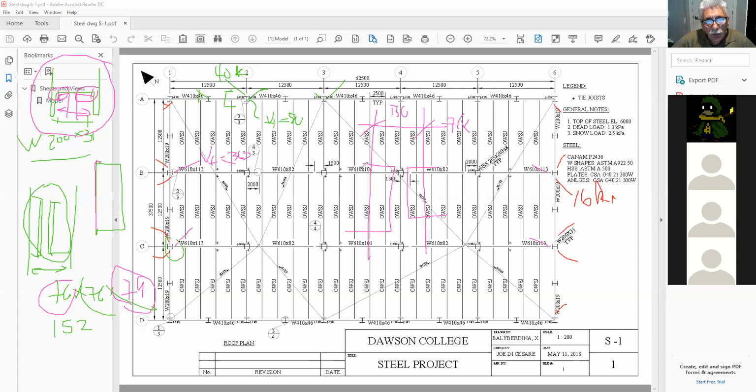So how am I going to be able to weld here if I'm past the column? That's something you have to consider: you have to stay within the width of this flange and be able to provide the welding so that your supporting angles can be welded to your column.